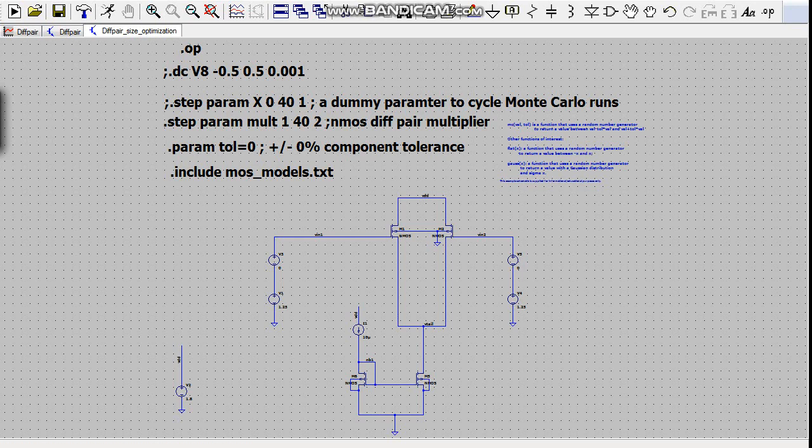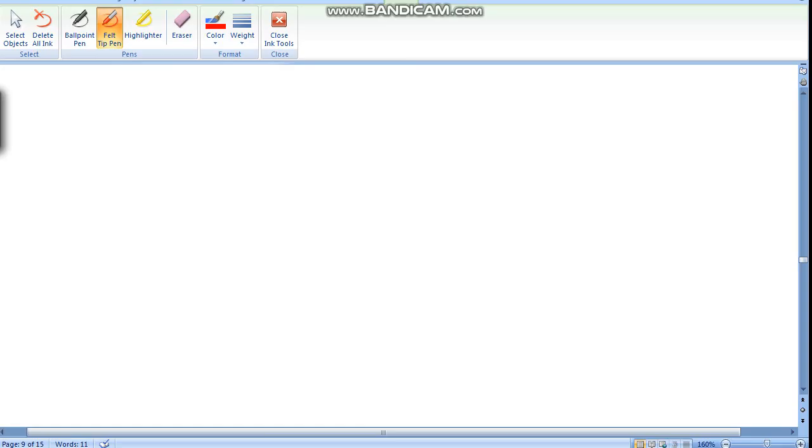Hello friends, in this video we will see size optimization for differential pair as per bias current. So what we are going to do, first I will explain here. We will take a diff pair and we have some tail current, this is some bias current, I bias.